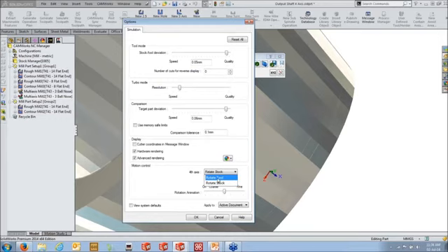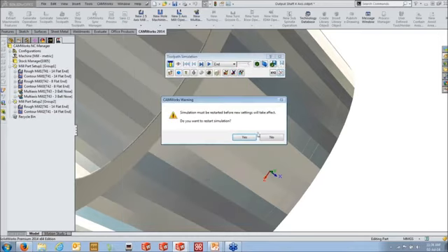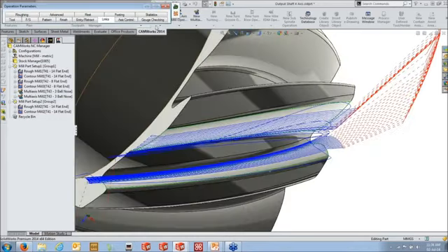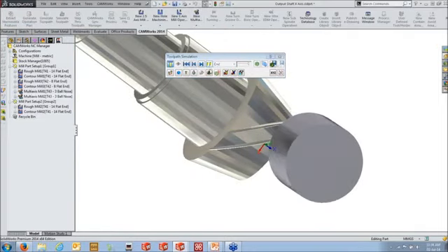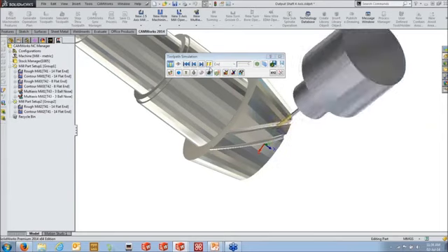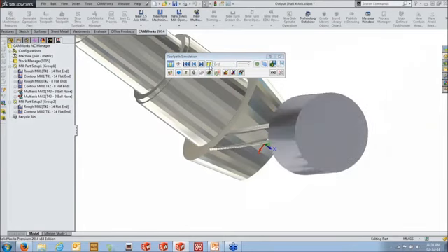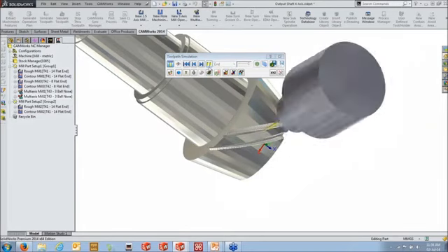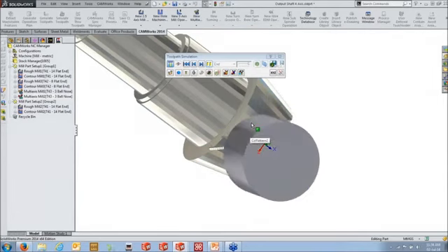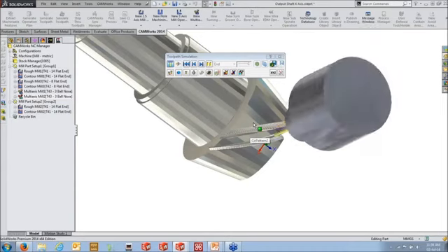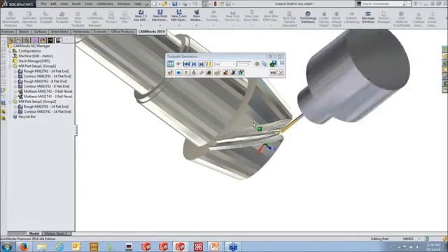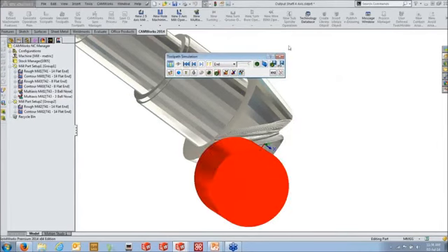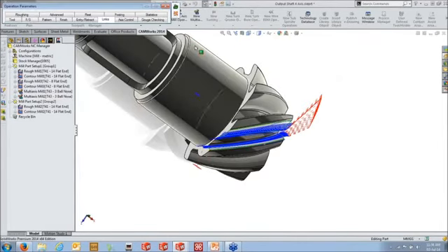If I switch it to rotate tool, you'll still see in the multi-axis operation, it's still going to do this. That's really where the machine simulation would come into play. That's where you can get a much better idea, particularly if you're doing more of this stuff. It's much clearer because you can set it up to rotate. You can check out all your clearances. If you're going to crash potentially somewhere, that's where you can see it, in the machine simulation.